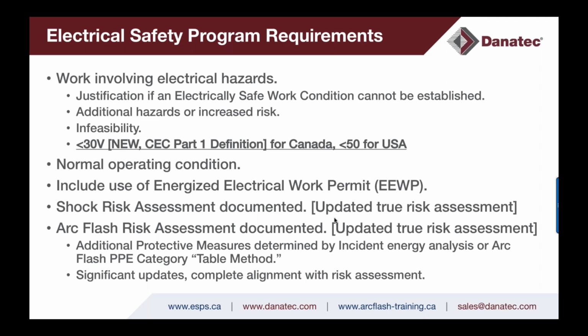Your electrical safety program, and the next bullet says normal operating condition. This was in the 2015 editions as a clause in an article, and it's very important. And I have conversations quite often over the last several years since this concept of normal operating condition was identified. I think I've always talked to clients about normal operating condition, but the controversy is, well, how do we determine normal and abnormal operating conditions? And basically, we can use the definition information in 70E and Z462, and part of the electrical safety program should be validating that your company has a normal operating condition right now for your energized electrical equipment.